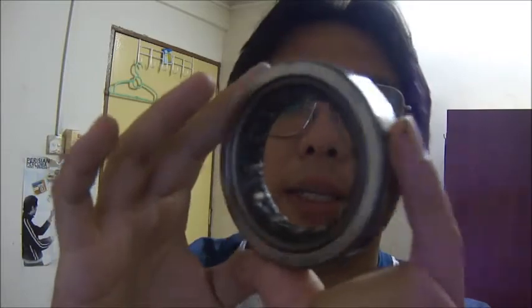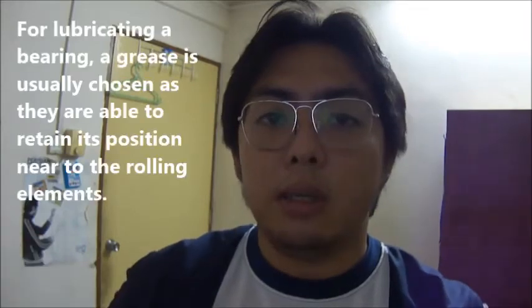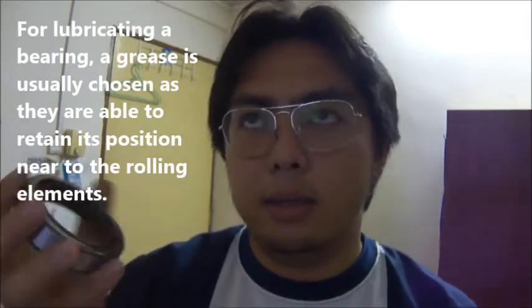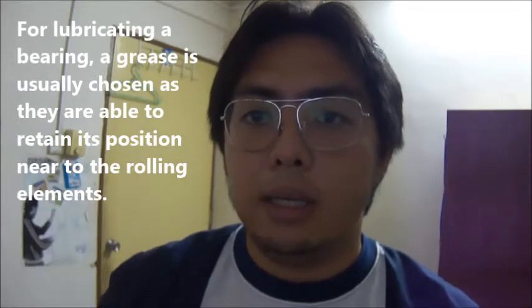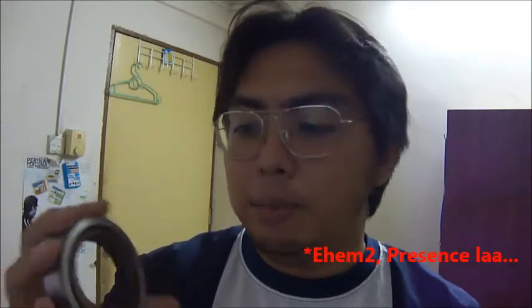This is an example of a rolling bearing. It has cylindrical rolling elements, and if you look between the rolling elements there is grease. This grease helps in reducing friction when the bearing is in use. So what is grease? Grease is a lubricant for bearings. It lubricates moving parts, usually where metal to metal contact is present. It is made thick so it will stay in place and not leak out from the bearing seal.